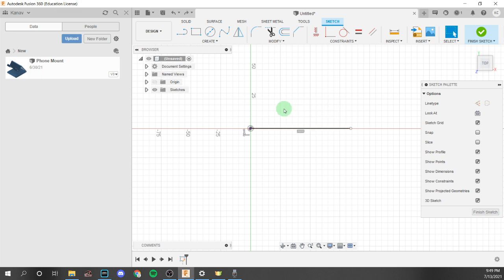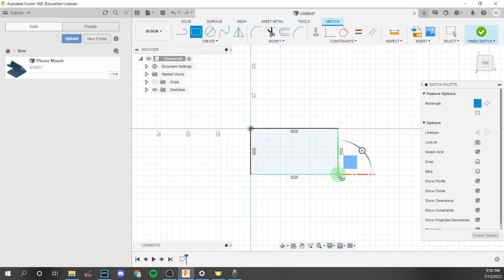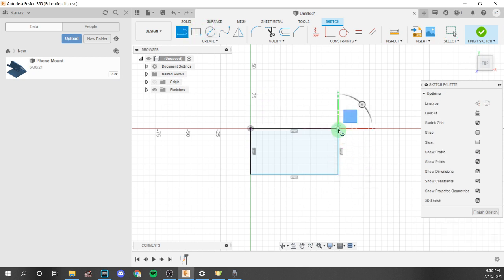Now this is very helpful when, let's just say, you want to extrude a surface and you have to select like 50 different shapes or 50 different shaded areas. Construction can make it so that you would have to select fewer areas. Now to give an example, let's say you're drawing a random shape where you're doing here and here and here and here, and you want to make this one thing. You would select this and you would turn it into a construction.